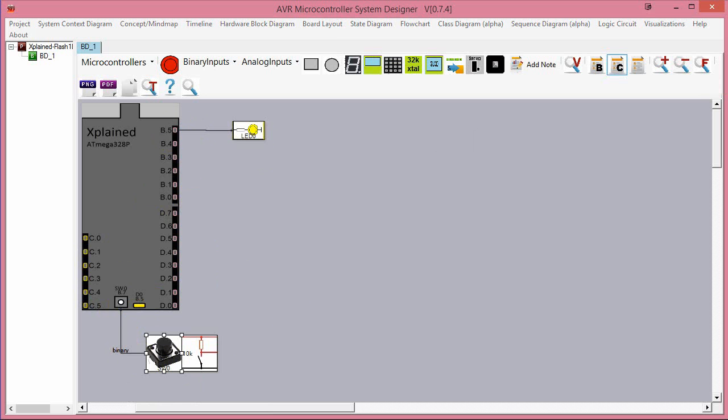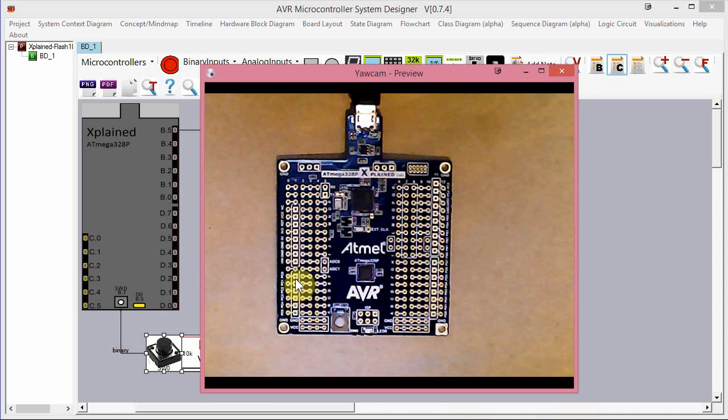So if we go back to the webcam, you'll see that there are 6 here, and they are C0, C1, C2, C3, C4, and C5. So that's port C. Over here, we've got 8, which are port D, from D0 through to D7. Up here we have quite a few places for soldering things into, but 6 of them are connected to the microcontroller directly. That's B0 through to B5. So that's these lower ones here. The others have got voltage and things on.